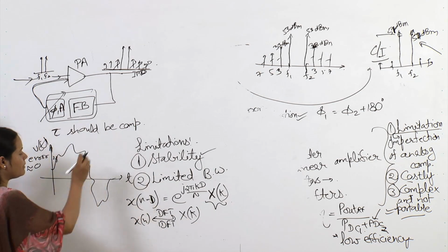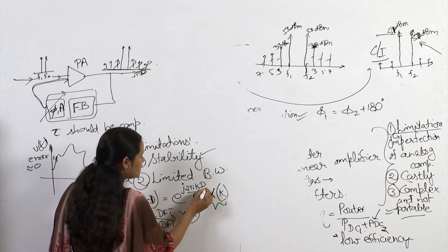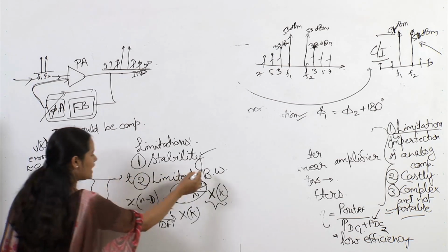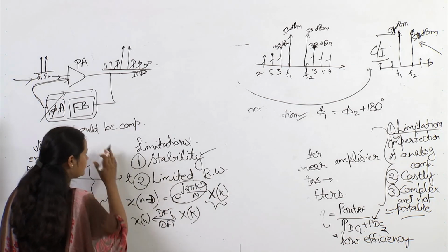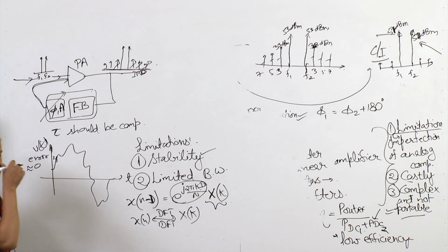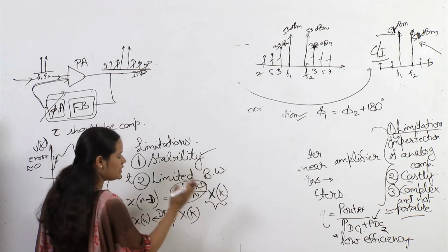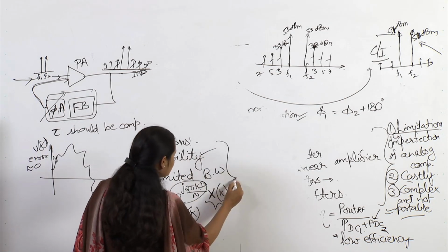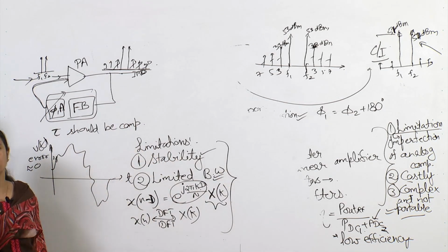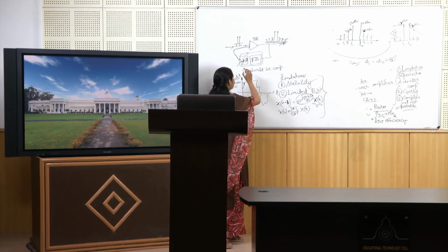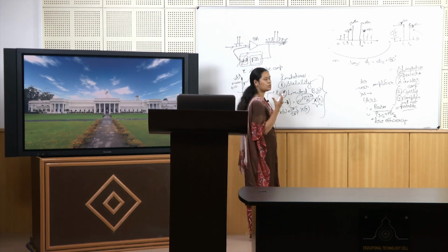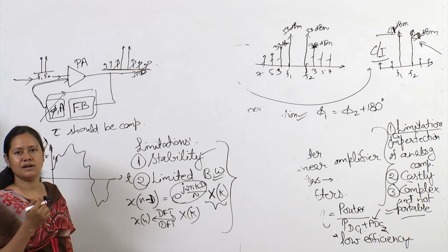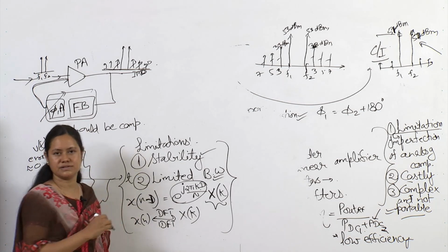But when a signal is coming from a delay, then it appears as a function in frequency domain, a component in the frequency domain. So, we cannot go to higher bandwidth because those bandwidth will be representing actually a delayed signal here. So, they will interfere with each other. So, if it is a single carrier signal, it is okay because this kind of components will be falling nearby the actual tone, but if it is a bandwidth signal, then we will have distortion components which will be interfering with this. So, because now we are going for the very higher bandwidth signals when we are moving from 3G, 4G towards 5G, this feedback scheme is not that good scheme, especially when we want to have a system which will keep working continuously. There might be jitters, there might be other effects which we cannot control, effect of atmosphere, temperature, etc. So, it is not a very reliable solution, although it is very portable solution.